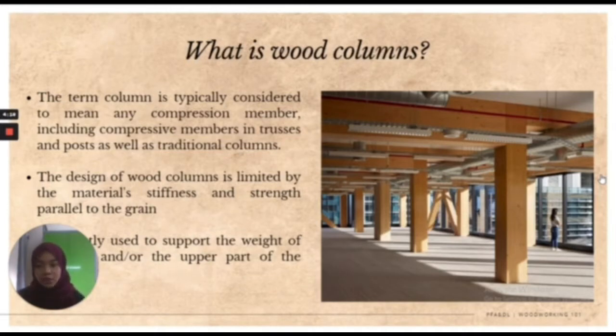In selecting a wood column, there are criteria that should be considered, such as lumber species, structural grade, modulus of elasticity, and shear stress values permitted for the intended use. In addition, attention should be paid to the precise loading conditions and the types of connection used.